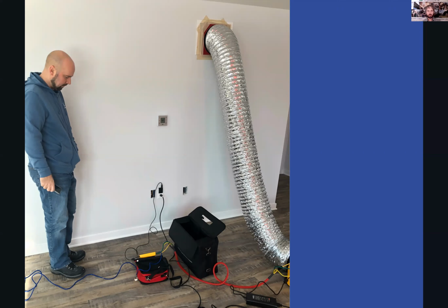You might not be able to make a certain program, like LEED. Energy Star and Enterprise Green Communities require that you have Energy Star level duct tightness, which is pretty aggressive, and Passive House as well. And so make sure you're testing your ducts. If you've got really cold rooms in certain areas of a house or a project, test the ducts to see how leaky they are and what can be done to repair them, so you have that information.